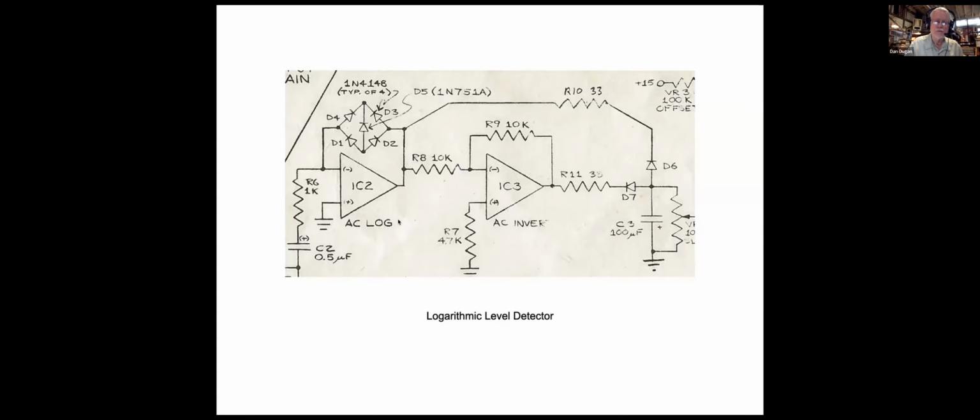And this was a circuit which was an AC logger, so it would squash the AC signal using a Zener diode as the element. I'm sure saturation plugins for workstations which imitate tape saturation probably are imitating circuits like this. It's full wave, and so you come out in a filter, so you come out with a DC voltage which is representing the level of the audio signal.